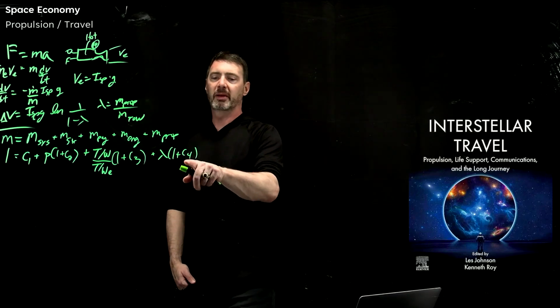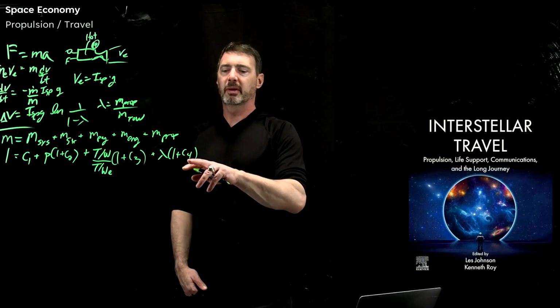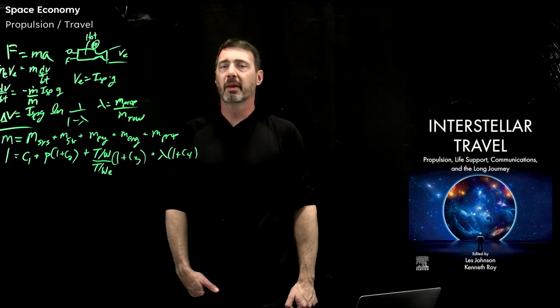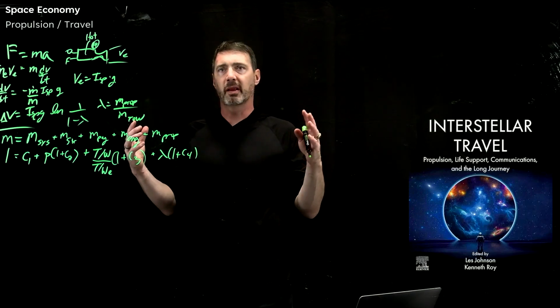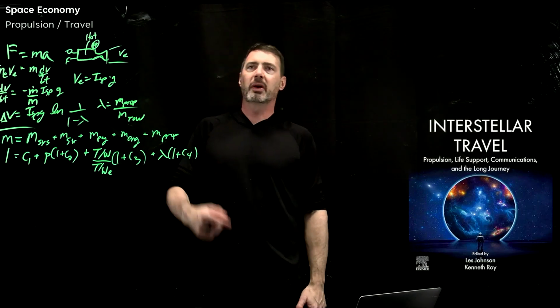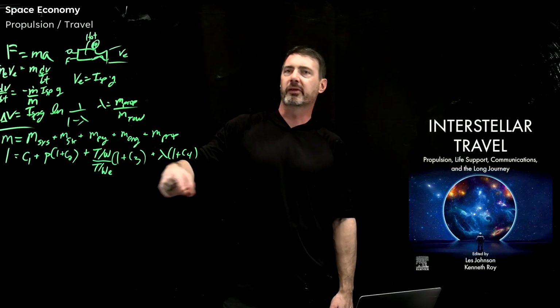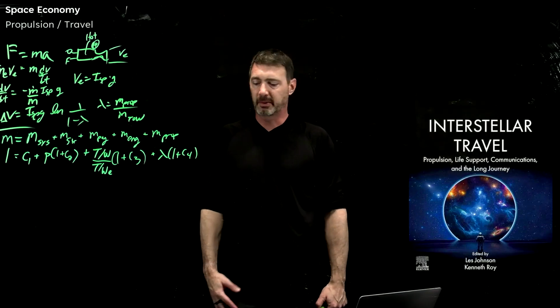Now you got to be careful because the amount of structure it takes to hold, say, liquid hydrogen could actually eat your lunch pretty good, versus dense propellants like liquid oxygen or hydrogen peroxide and things like that. So this is a system equation you got to pay attention to as well. In addition, we have sort of the performance equation, but this is the total systems engineering thing.